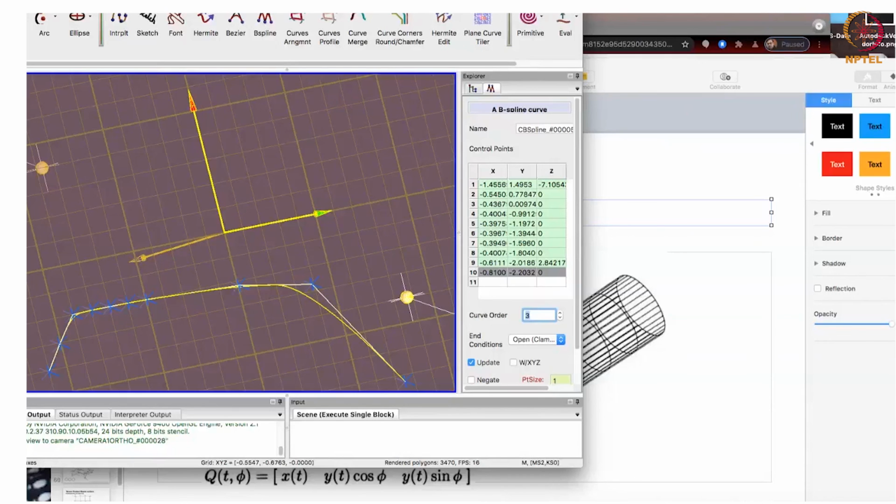Correct. You may think of piecing together one straight line with a parabola, and then on the other side of the straight line you can fix another cubic spline kind of thing. But each one is its own piece. You don't have a unique representation, a unique equation. As far as I can think of, generating such a curve or a surface is only possible using a B-spline surface.